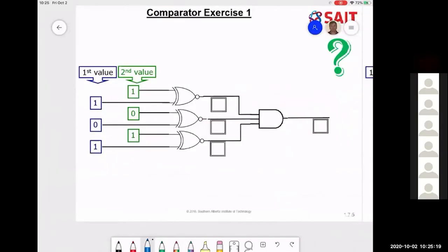We've got a 1 or a 1. If it was OR, we'd say, yes, that's true. But it's exclusive, so it would be false. But then we've got a bubble, so it's true. Okay, so 1 or 1 would have been a 1, but it's not exclusive here, therefore that would be a 0. But we have a little bubble on the end, so it's a NOT, so that makes it back to a 1 again. So it's a little more complicated than just doing it visually.